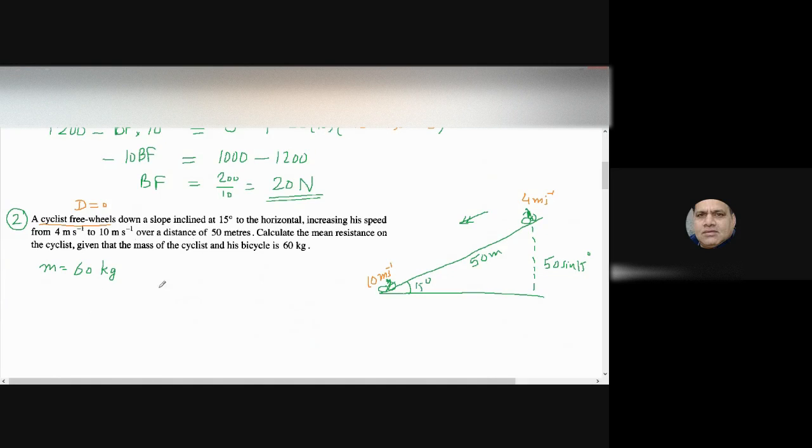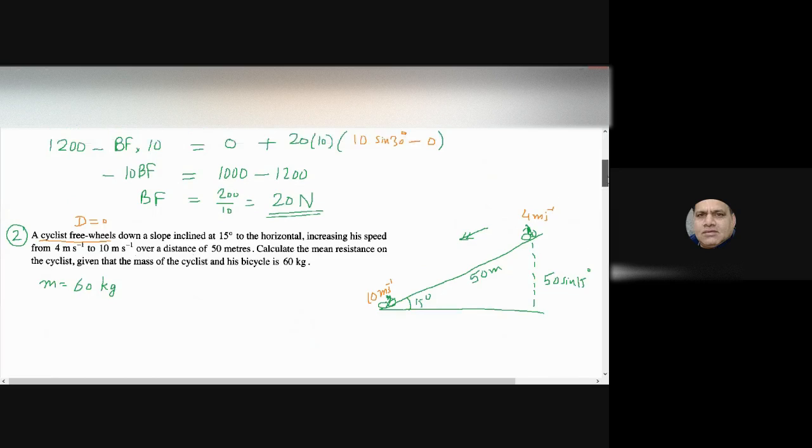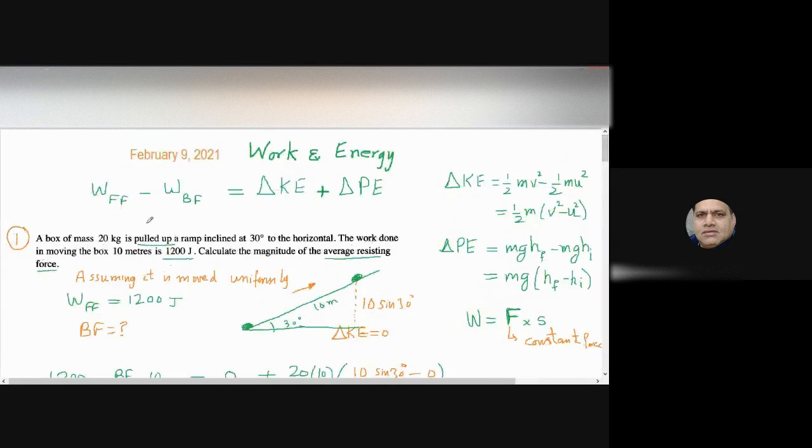And one important point I will write here: while using the work energy equation, never take the weight as a force.